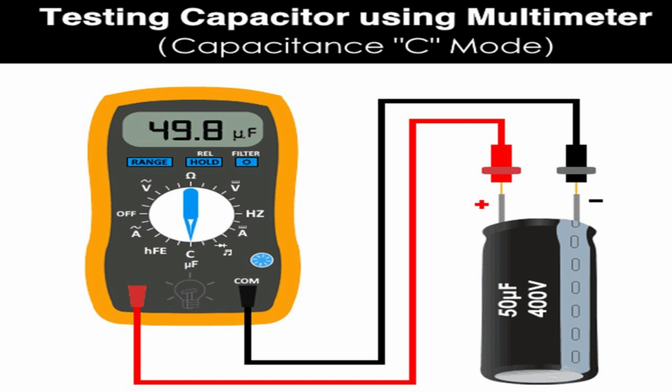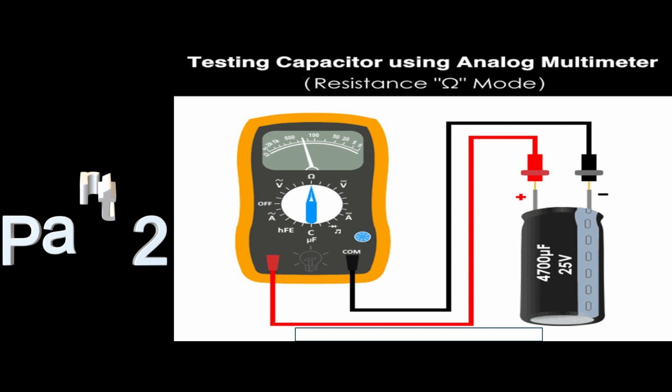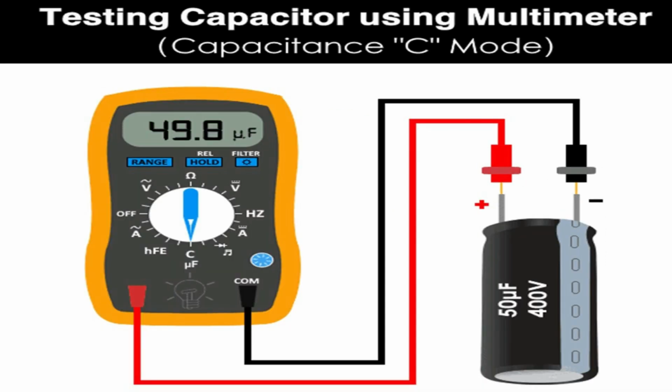The digital multimeter will show some numbers for a second. Note the reading. And then immediately it will return to the OL, open line, or infinity. Every attempt of step 2 will show the same result as shown in steps 4 and 5. It means that the capacitor is in good condition. If there is no change, then the capacitor is dead.